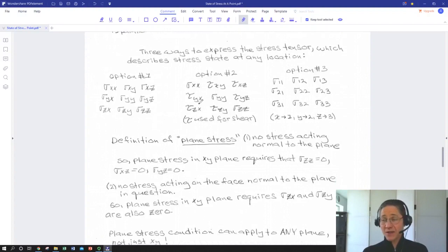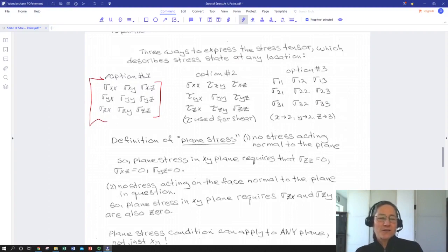All right, tensor notations. You noticed on our cube, we've got a lot of faces. We've got 6 faces, and on each face we have 2 directions that we can assign shear, and then we can have positive or negative axial. So this gives us basically a 3-column, 3-row matrix, a tensor as opposed to a vector, to express our stress. So we can write it many different ways.